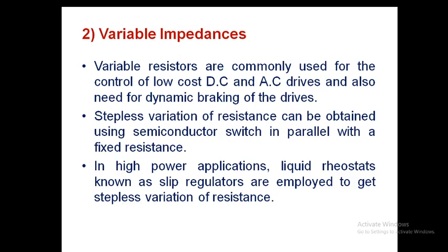Again, in higher power applications, liquid rheostats known as slip regulators are employed to get stepless variation of resistance. Generally, in higher power applications, if you use a variable rheostat, it will consume more power. That power is wasted as heat. So for that, we use slip regulators to get stepless variation of resistance.